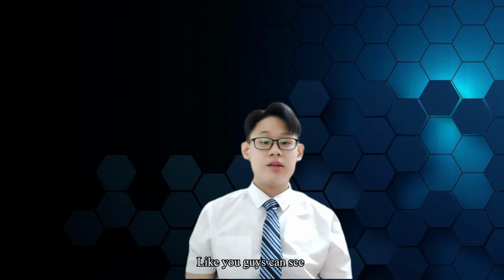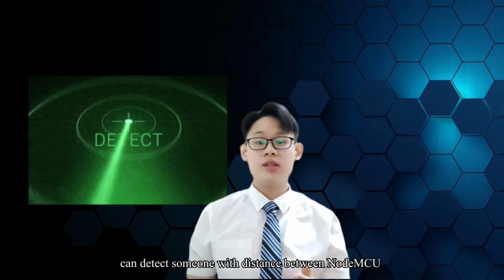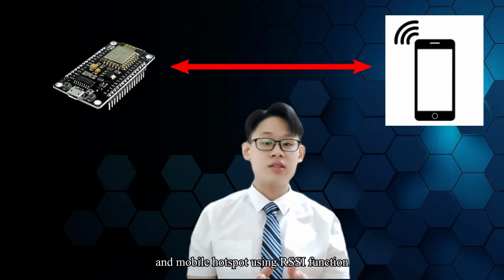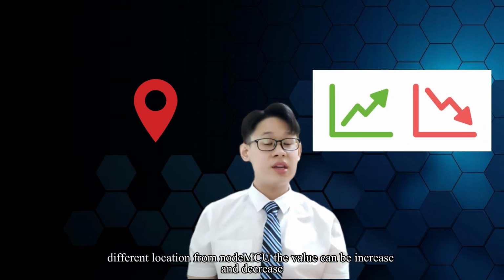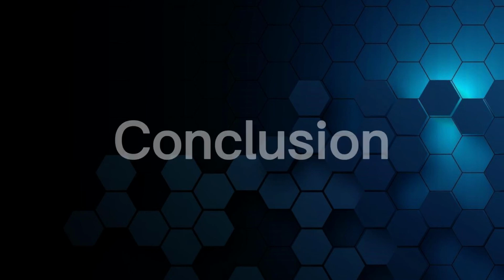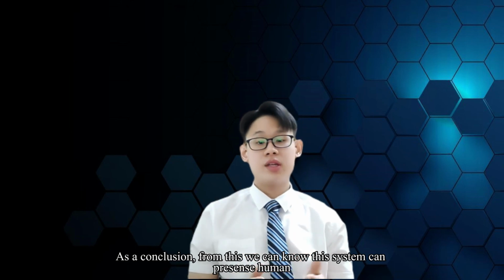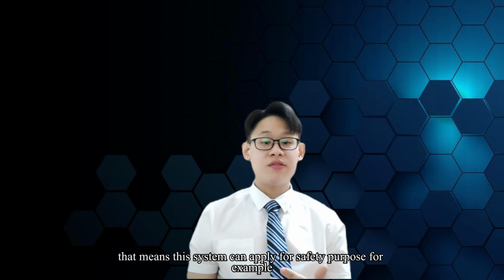Now you can see that the system that I have developed can detect someone with the distance between NodeMCU and mobile hotspot using the RSSI function. When the mobile hotspot is located at different locations from NodeMCU, the value can increase and decrease. As a conclusion, from this we can know this system can detect human presence. That means this system can be applied for safety purposes.